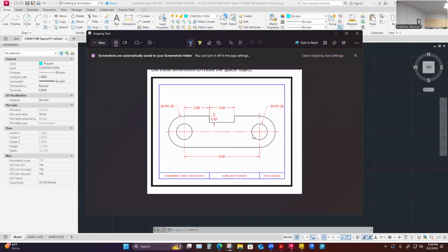So the actual hole diameter here is normal on entire holes that are shown with the diameter symbol. And when I'm considering an incomplete circle, it's going to be with a radius given. Okay, so I'm going to start with that. I'm going to start with just this, and then I'll worry about this little notch later.